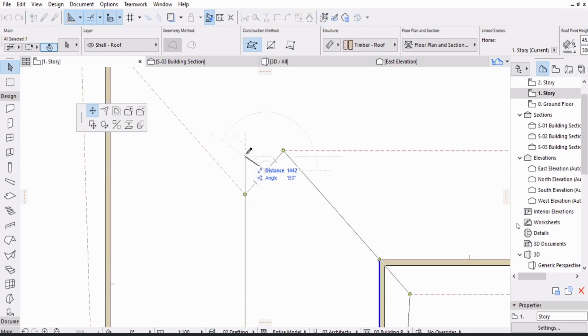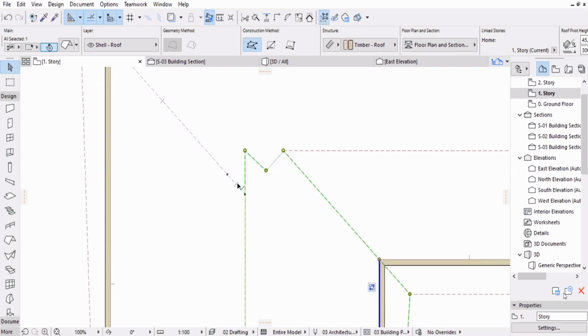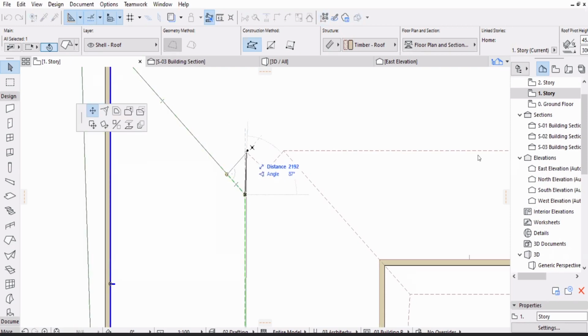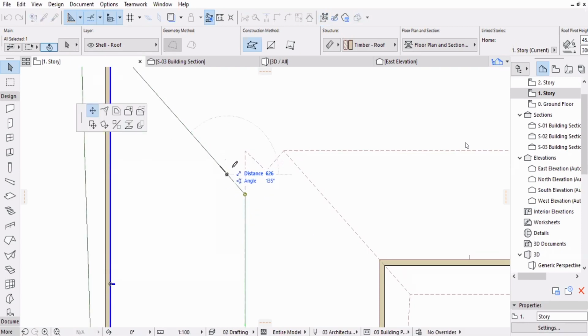We just move this point in line with this and then shift this. You need to move this point first along this ridge. So hold shift as you're moving this along this. It's not matching up. So hold your cursor on this so that you're able to draw an imaginary line here on this, and then you can move that point onto that.